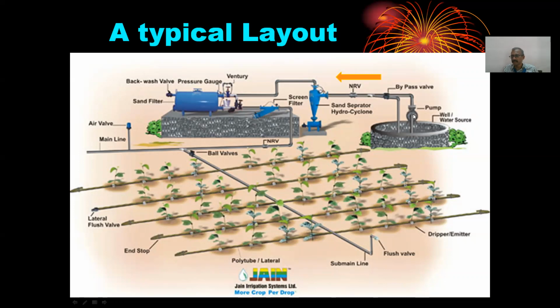But there is a possibility of problems with your bearings. At the impeller you have a bearing, and that impeller bearing may sometimes cause leaking. So in that case, it is better to use the bypass valve itself instead of just a GI control valve.